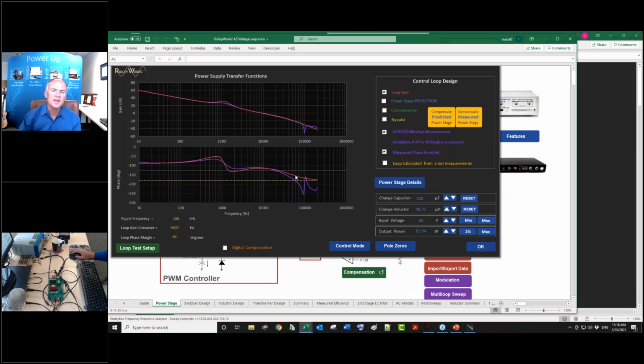Do you worry about these differences? Well, you can try redesigning this and making the final capacitor of the compensation a little smaller to pull the phase up. Or you can say, well, I'm crossing over here at almost 10 kilohertz and the phase there is just about perfect. But now you're in the dilemma, okay, do you work harder on modeling? You can't work any harder on measurements. It is what it is. And we can't account for that Q difference. And we can certainly work on the op amp model a little bit, but it is what it is.